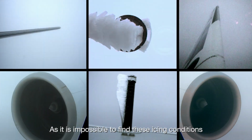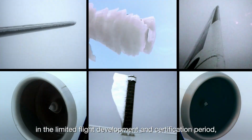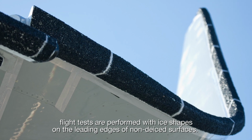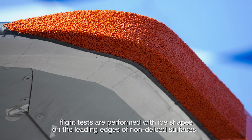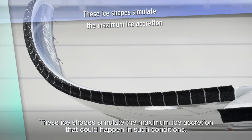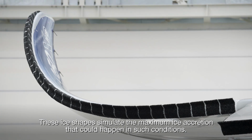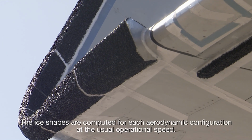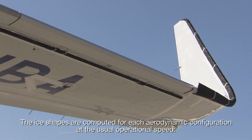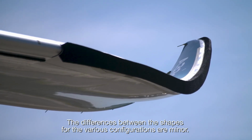As it is impossible to find these icing conditions in the limited flight development and certification period, flight tests are performed with ice shapes on the leading edges of non-de-iced surfaces. These ice shapes simulate the maximum ice accretion that could happen in such conditions. The ice shapes are computed for each aerodynamic configuration at the usual operational speed. The differences between the shapes for the various configurations are minor.